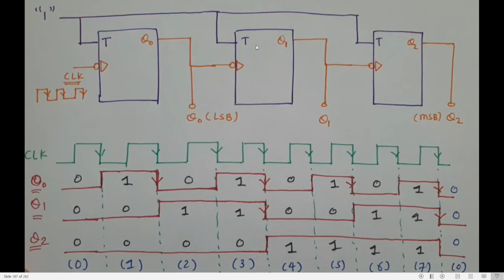Okay. Now we will see what is Q1. So what is Q0? Whenever there is a negative edge in the clock, during that time what do I do? The previous state will be toggled. Here the previous state was 0, I assumed it to be 0, so I toggle it to 1. Till which time will I be in 1? Till I get the next negative edge.